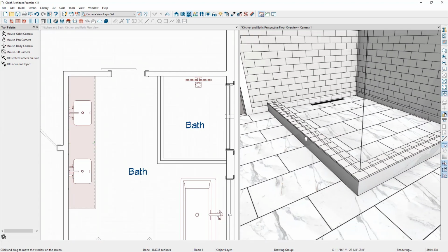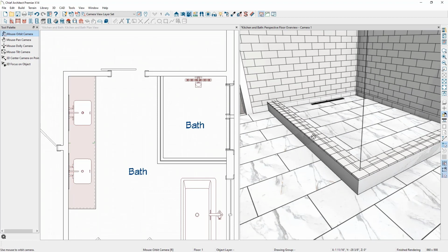And then the next thing we need to do is get the wall cap to match the wall material. So we're going to go up to the material eyedropper, select the material off the wall, make sure we're just in component mode, and then click on the wall cap. And there we've got that wall complete.